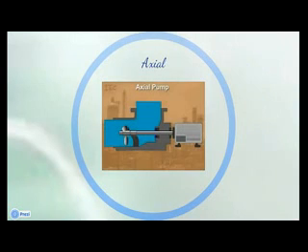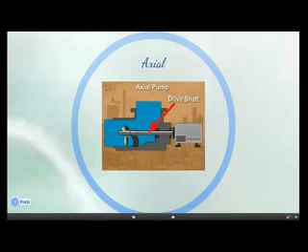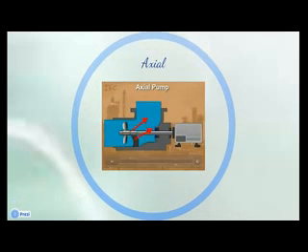Axial pumps move fluid in a straight line. Most axial pumps are located at an elbow in the piping system. A drive shaft extends into the process flow with a propeller attached to the end. When the propeller turns, the blades pull the fluid down the shaft line.